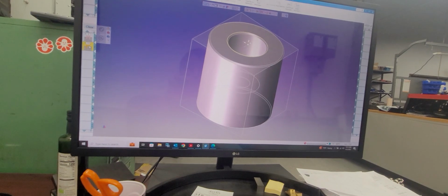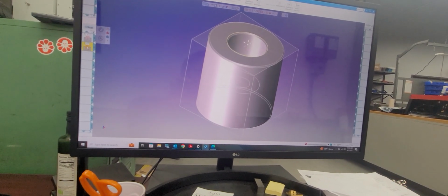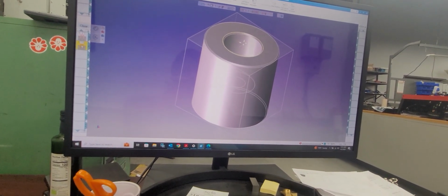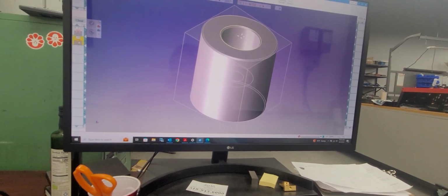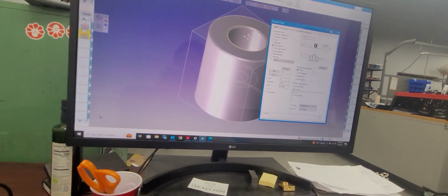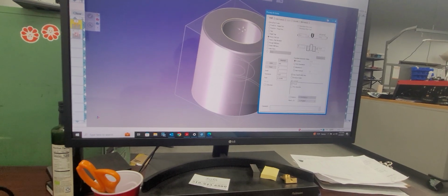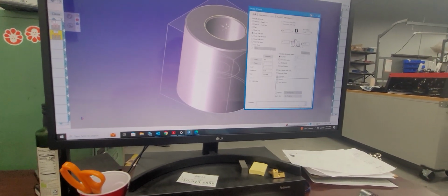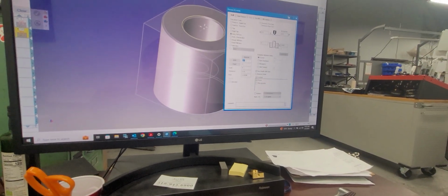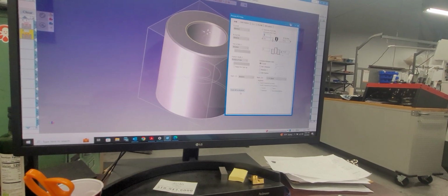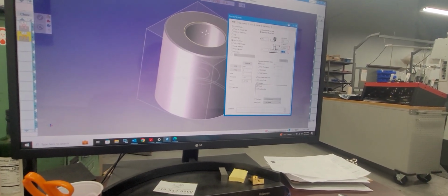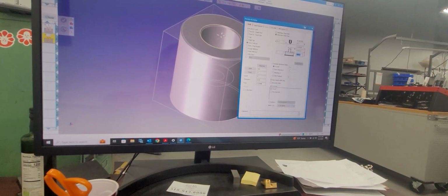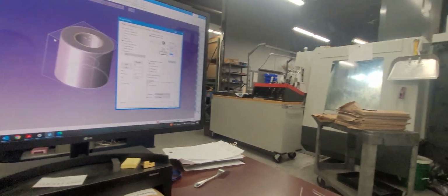It's always conclusive. And then when I run that, as I run graphics, it'll alarm out if that tool's not in there. That will probably prompt me to put it in. But over here now, I've got my spot drill ready. All I'll do here is adjust my SFM to suit and then give it a depth over here. And then once that's done, boom, that's it really.